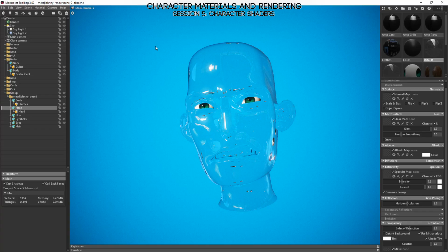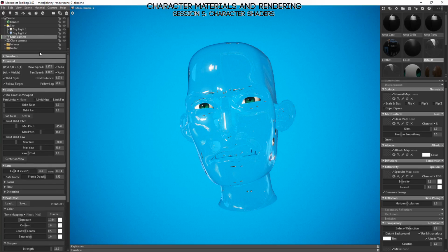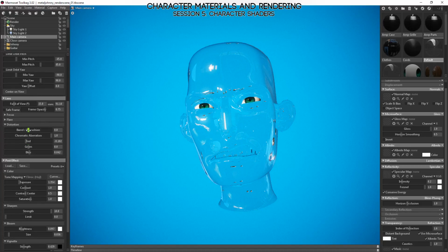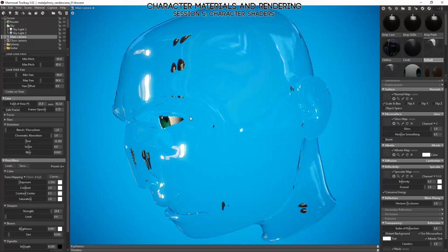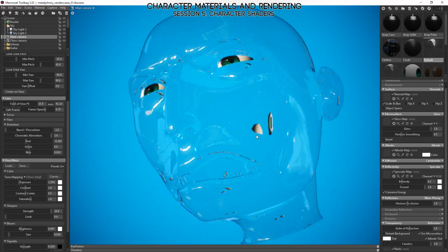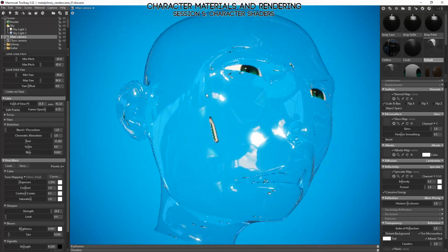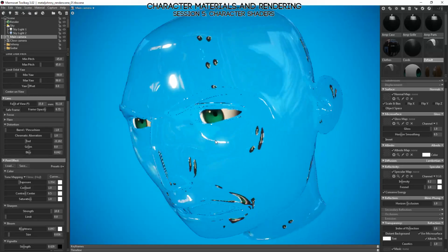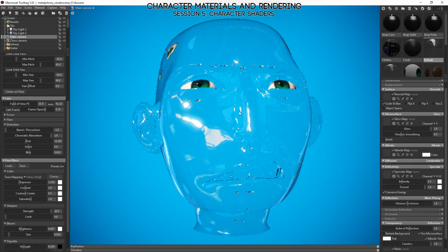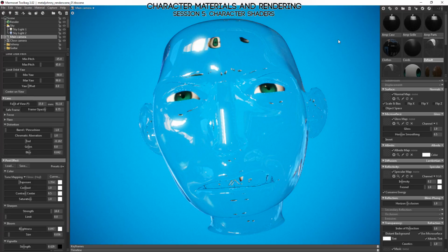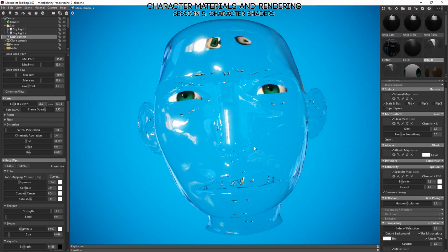Let's take a look at another example of a screen space effect to get a better idea of what we're talking about. If I go into the camera settings here, I can apply a screen space effect to the entire screen in the form of distortion. Here I'm applying barrel distortion to the scene. This is a screen space effect that basically says I want all of the pixels in the middle of the screen to look like they're bulging outwards. Now, if this was an effect based on a physical camera, you would end up seeing a lot more of the scene outside of here if there were other props and such. But in this case, all it's doing is sampling whatever is on the screen and transforming it somehow.